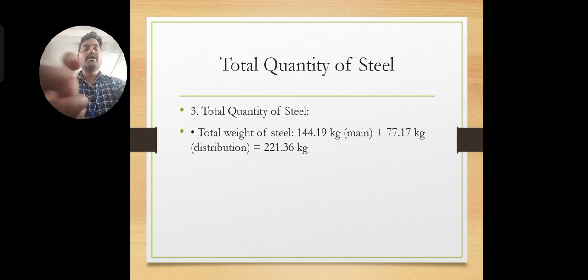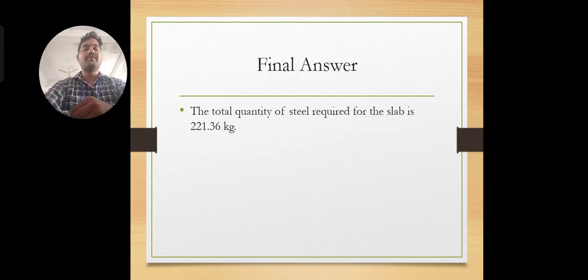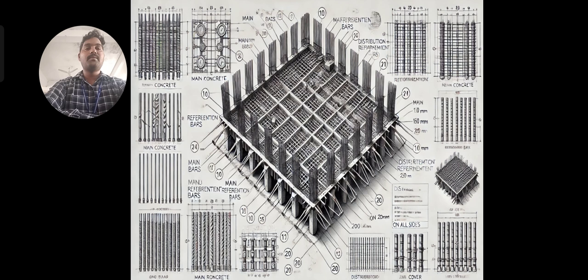And now in a similar way, the final answer of the slab quantity is required, and you see here the arrangement of the bars as per the details given. The main bars are always provided width wise, but the distribution bars are always provided length wise. We should also know that the spacing should be followed. Finally, this is an arrangement we can do, and only after doing this arrangement are we going to pour the concrete in the slab.